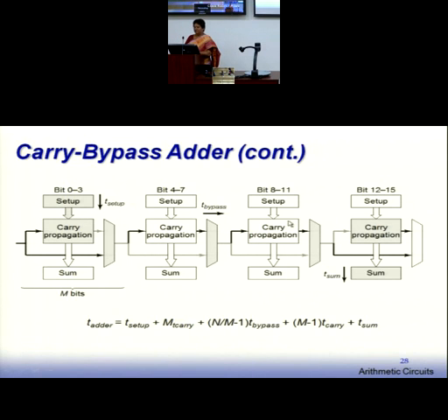Then 1 unit delay for computing the P04. By that time, what is this doing? It will be the GP functions, individual calculation, then 1 extra step for computing P04, and then it passes through this mux. Another delay will come, and then C out is generated.